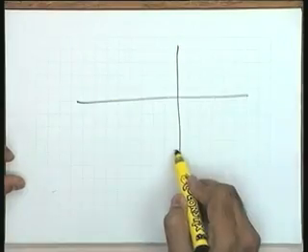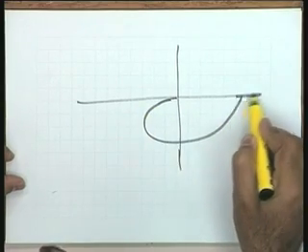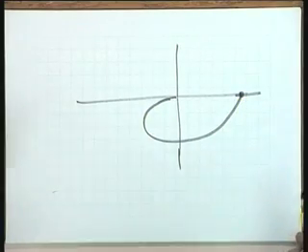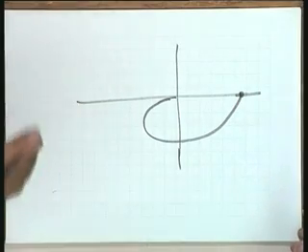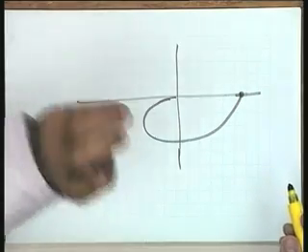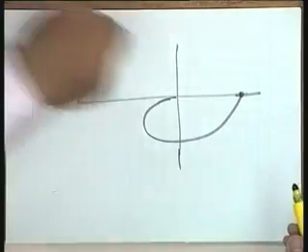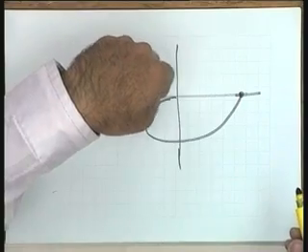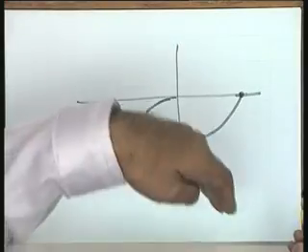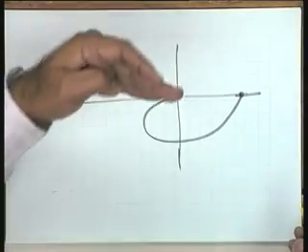Recall the polar plot. The polar plot is the following. Whenever I use the word polar plot, please note that I am making the actual frequency plot. Omega equal to minus something has no physical meaning, frequency is positive. When you are taking omega equal to minus something, you are actually taking the mirror image, from the point of view of mapping the negative axis which is required by the Nyquist stability criterion.